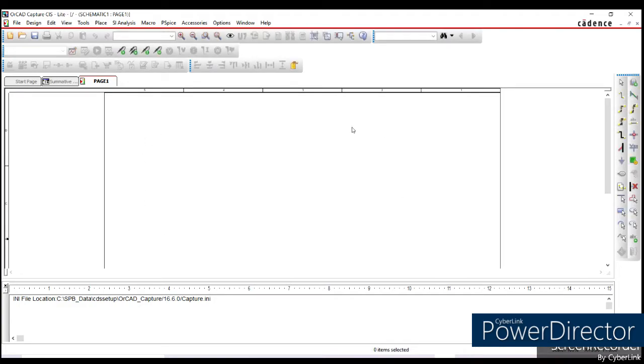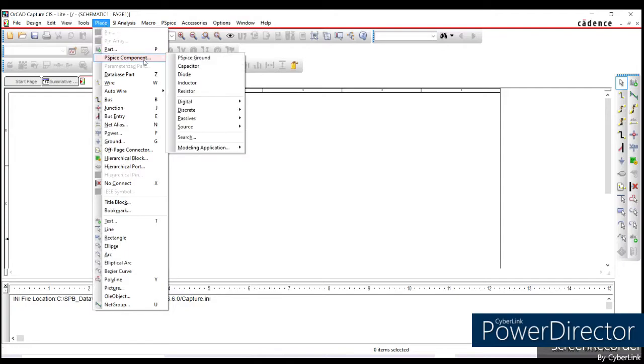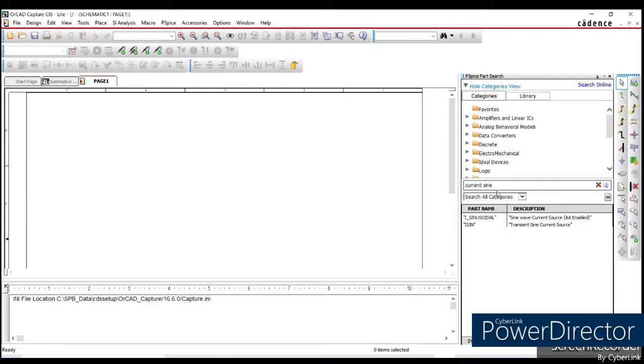Before proceeding with creating our schematic in PSpice, later on I will be showing and explaining the calculations for the theoretical values for each of the conditions so that we will be sure that they match our measured values using PSpice. If you can still remember, our given is an AC current having a value of 5 sin 2πft. So considering the AC value, we will be placing a current source, which will be giving the circuit an AC current supply.